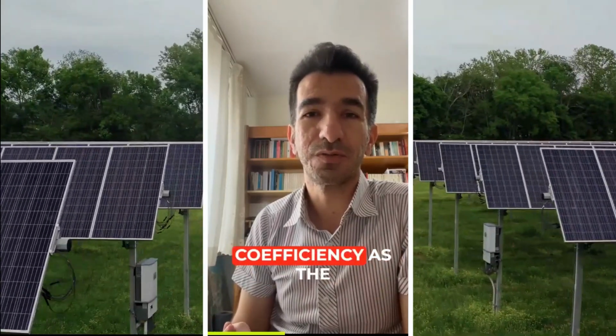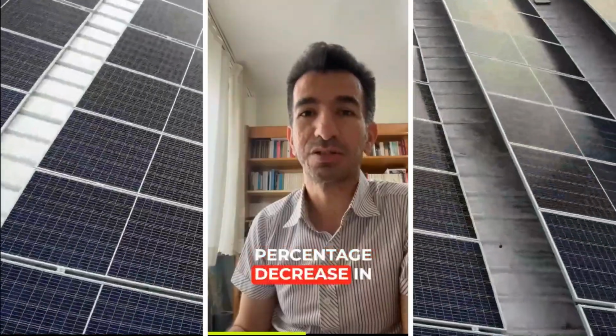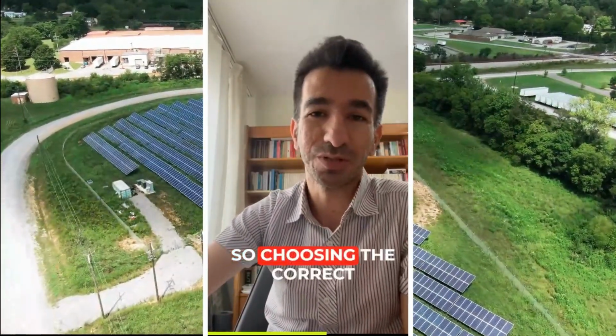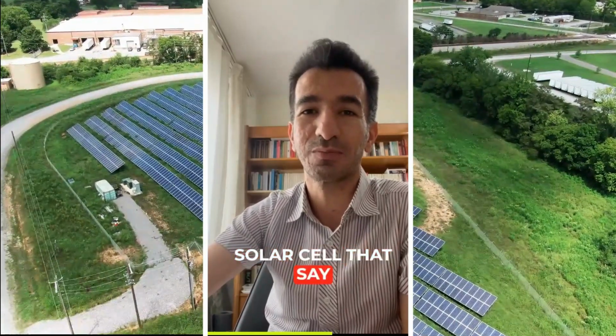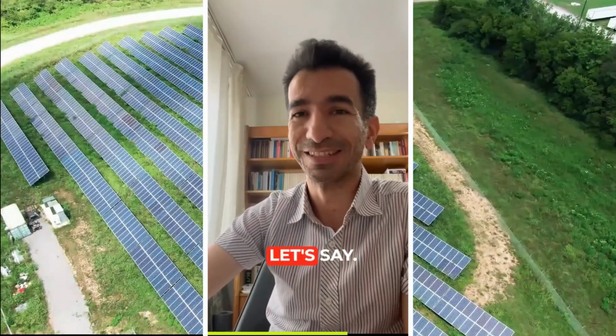One of the main factors is the temperature coefficient. Most solar cells experience a decrease in efficiency as the temperature increases. This is often expressed as the temperature coefficient, which is measured as the percentage decrease in efficiency for every degree Celsius increase in temperature. The temperature coefficient varies among different types of solar cells, so choosing the proper solar cell is really important when you want to design your solar power plant, let's say.